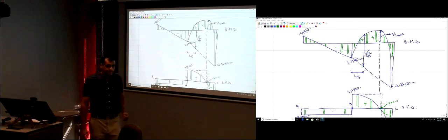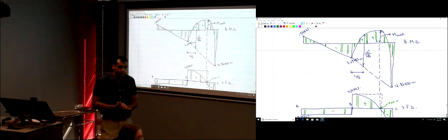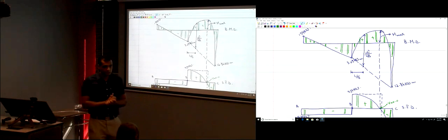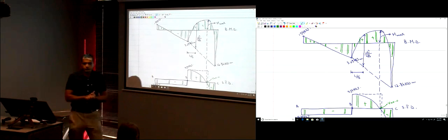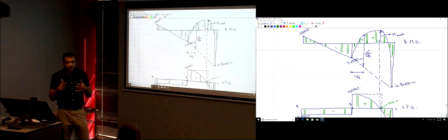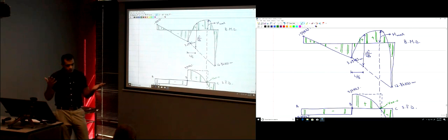Yes? Whenever you're using the equation of equilibrium to find your forces in the y direction, were you just assuming the positive and negative on the moments? Yeah. You just assume it? Yeah, no set rules, just assume. Just assume anything, and then after that, you also assume the vertical forces. So if you get a positive sign for those vertical forces, your assumption was correct. If it's negative, then your assumption was wrong.